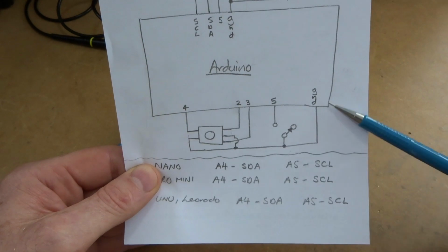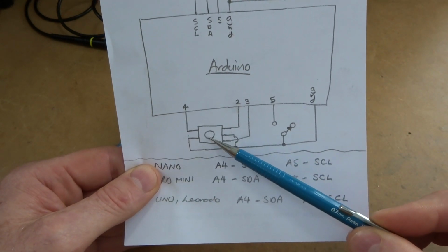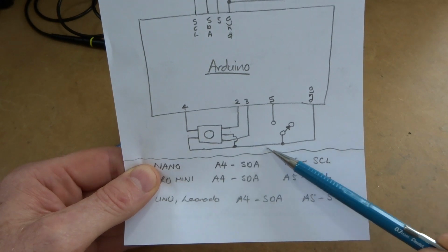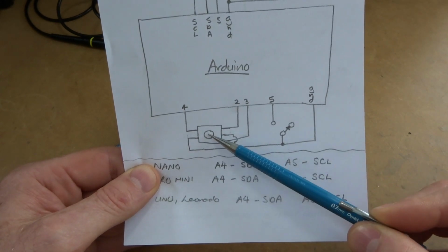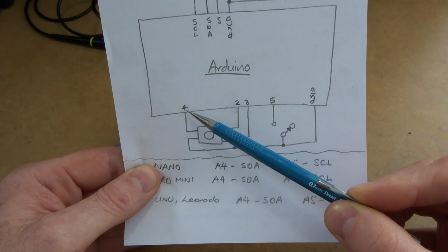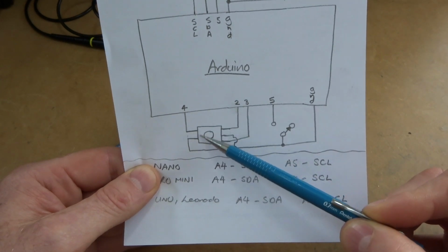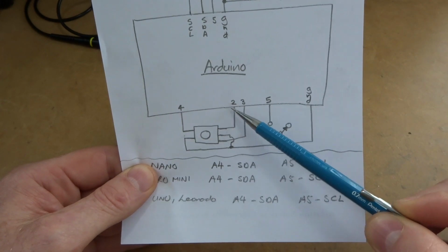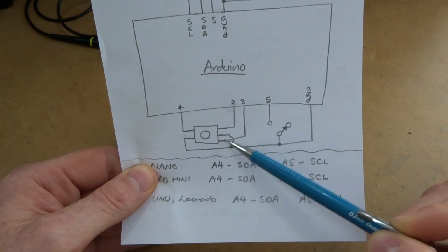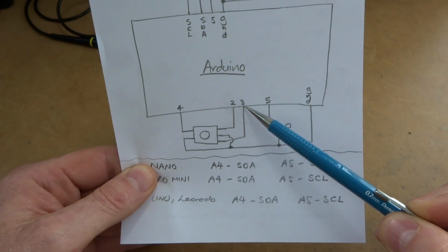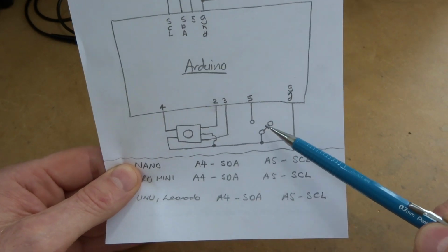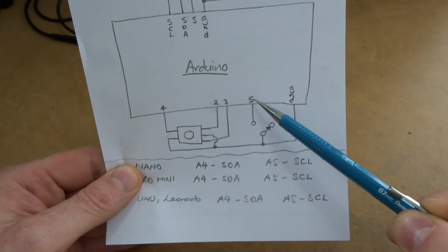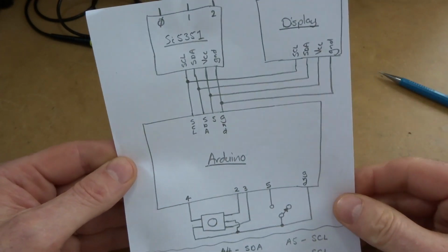In terms of the individual pins for the rotary encoder, the push button switch, one side goes to earth. So when you push that switch down, that earthing gets applied to pin 4 through the internal switch. On the other side, those 2 output pins from the rotary encoder go to pins 2 and 3 in the code that I've got. And like I just mentioned before, that band switch goes to pin 5. So that's all I wanted to cover off from there.